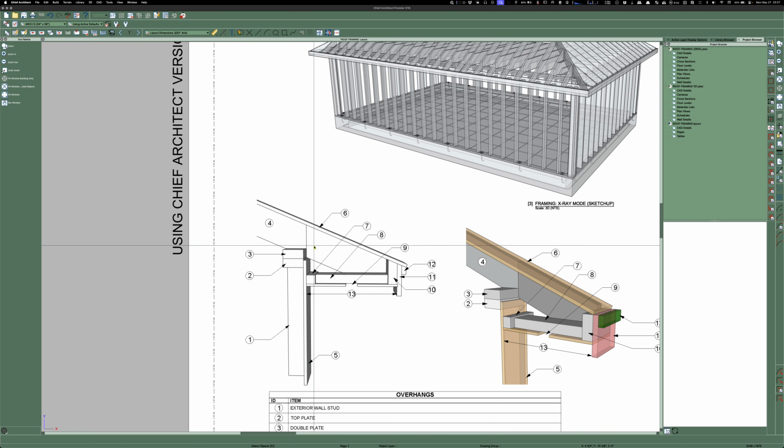So you rip a 2x4 tail, or mostly it's trusses. They come with the 2x4 sticking out here, wild, about 24 inches. And you cut it back to whatever your exposed overhang is going to be. And you take your fascia board and you nail it straight onto the tail, which I've never liked, because now you're just putting a couple nails or a couple screws into the end of each tail. And that's not going to hold up very well, it's just not.